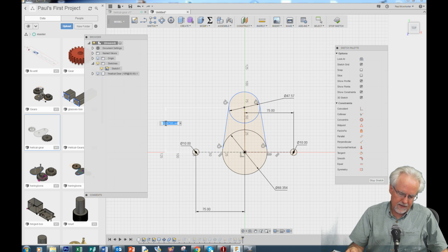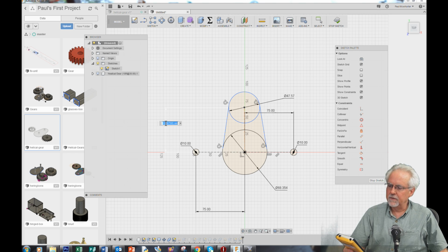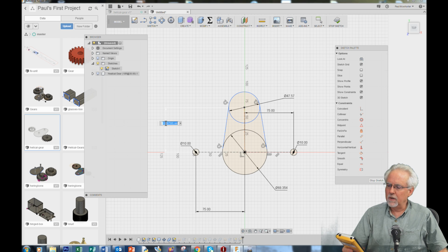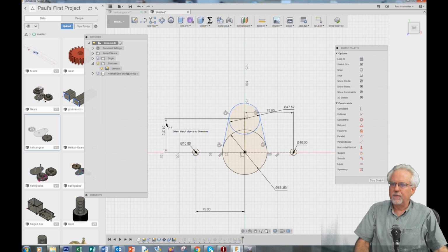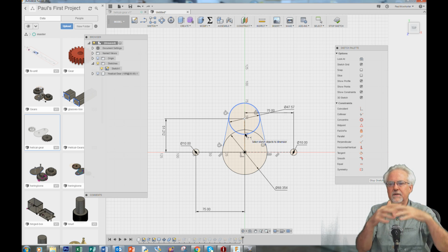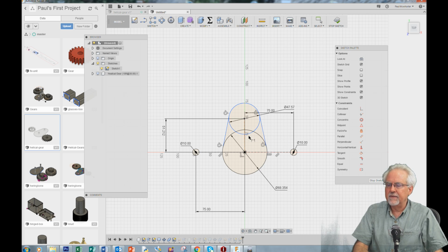Now I need to add to that 34.07, that's the diameter, divide by 2, that's the radius. Okay, and what do I get? I get 51.212. I guess it would have worked either way, but 51.212. Okay, boom. What does that mean? That when I put this gear and I put this gear, do you see this overlap? That's the overlap of the teeth. So if I just visually look at it, that looks good.